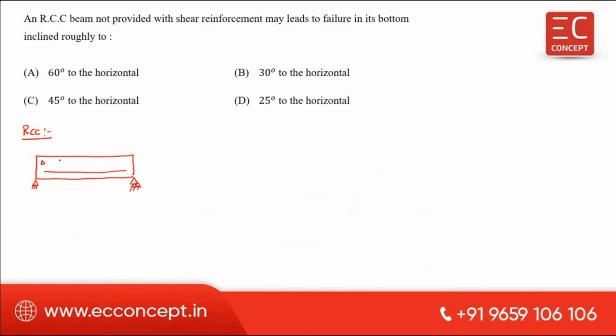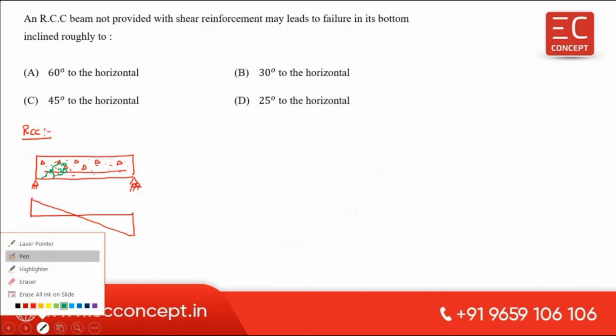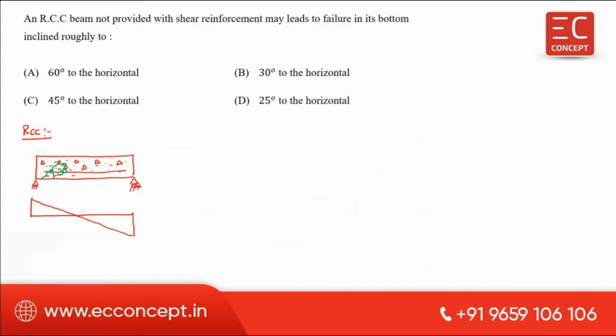Then we have concrete. Now, if you see the shear force diagram, you will get something like that in nature. Now, you know the shear crack will be developed with respect to the horizontal at 30° for RCC. So consider a point somewhere here.